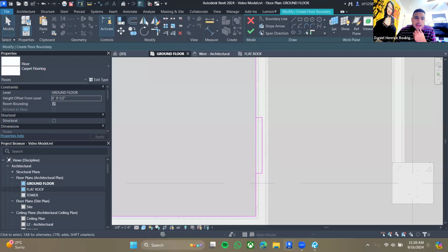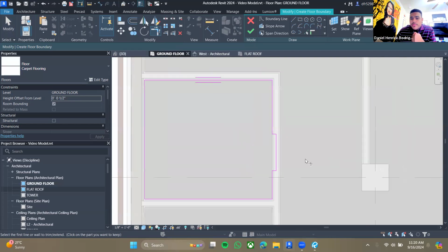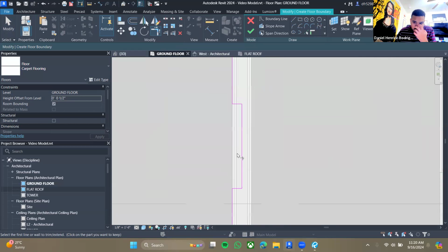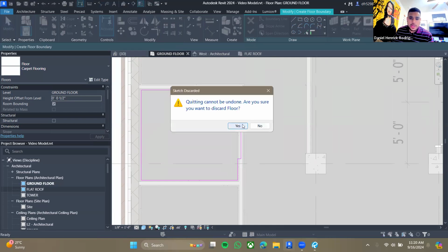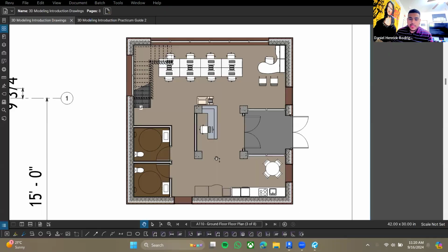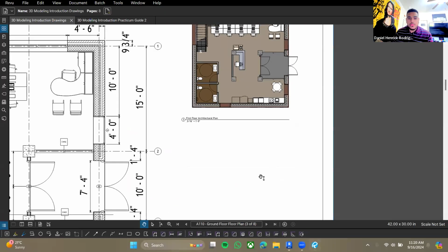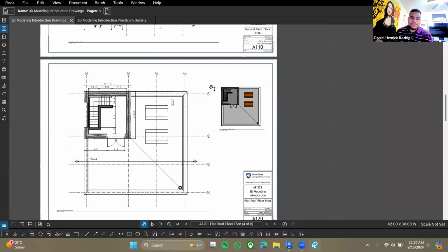do that part, right? Whenever you have a door, you're gonna have to make these cutouts so that the floors connect. Otherwise, you're gonna have your bathroom flooring, your general area flooring, and there's just gonna be a concrete gap in the middle. So make sure that you draw these specific little areas where the doors are. Okay, I'm gonna click off of it because I was just showing you guys what you're gonna be doing. Okay, so we got floors. Make sure that you do those. Nope, there's no floor on the top. It's just concrete. Okay, what do I have next for us?